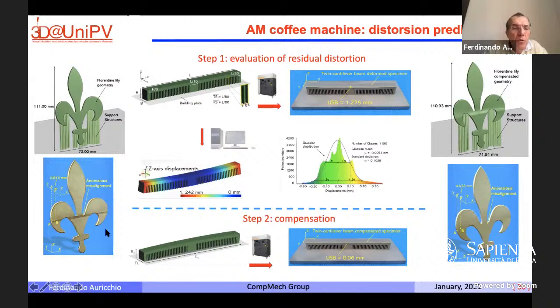And the first time that we produced it, we got a very strange behavior. Basically, there was a misalignment between the bottom part of the component and the top part of the component. And looking at the production, this was clearly due to some overheating in this region up here.